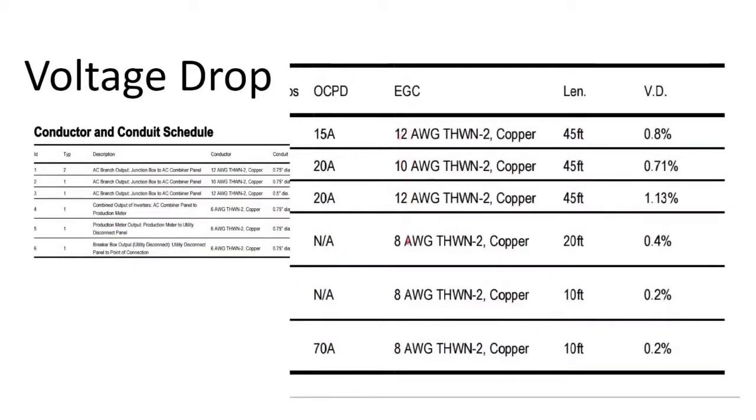You might be looking at this material list and saying, well, why don't we simplify it? And sometimes you can oversimplify, like using number 8 cable for every circuit just to only have number 8 cable. That could result in you spending too much money on your cable budget. But if there is just one oddball, saying, okay, well, there's 2 circuits of 12 and 1 circuit of 10, but look, this circuit of 12 actually has some voltage drop to it, so let's make it a circuit of number 10 AWG instead, for voltage drop mitigation, and then